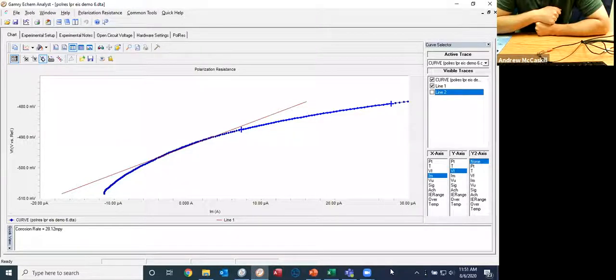With a potentiodynamic scan, where you're going 1 or 2 volts, you certainly are modifying the surface, but that's what you're trying to do. You're trying to pull out information due to that. In an LPR experiment, you don't want to cause a vast change in the material. You just want to perturb the system enough so you can figure out the I corr value. It's a very small perturbation just so you can tease out the Rp value to get the I corr.